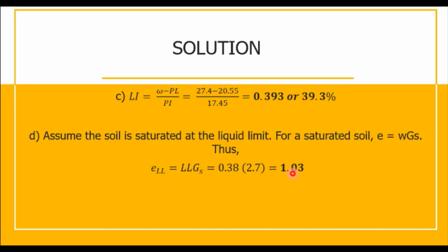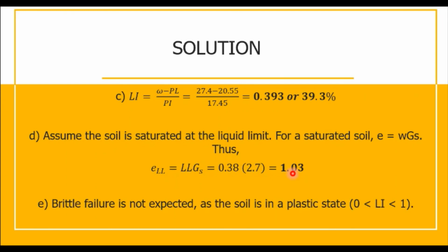And lastly, will the soil experience a brittle failure? The answer is no. Brittle failure is not expected as the soil is in plastic state because the liquidity index lies from 0 to 1. And therefore, that would be the answer for problem number 1.